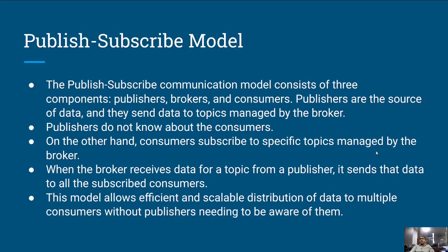The next communication model is the publish-subscribe model, which we discussed previously. Like we discussed in the case of MQTT, which was based on the publish-subscribe model, it has publishers, brokers and consumers. The publishers are normally the source of the data and they send data to topics managed by the broker. Publishers, however, do not know about the consumer. On the other hand, consumers subscribe to specific topics managed by the broker, and whenever a broker receives the data for a particular topic, it sends the data to all the subscribed consumers. This is a very efficient and very scalable model.